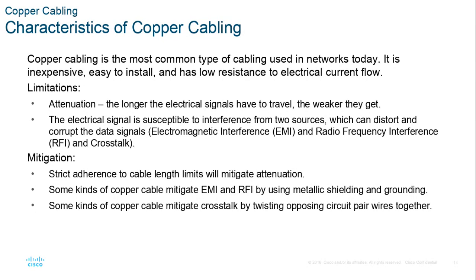But if you're at an auto manufacturing plant and there's a welding machine right next to you generating all these big sparks, we might need to use a shielded cable, because unshielded twisted pair can't handle that. Just like you know about PA systems and guitar amplifiers, all these wires that connect the guitars and microphones and bands together have to be shielded, otherwise they pick up a bunch of hum.